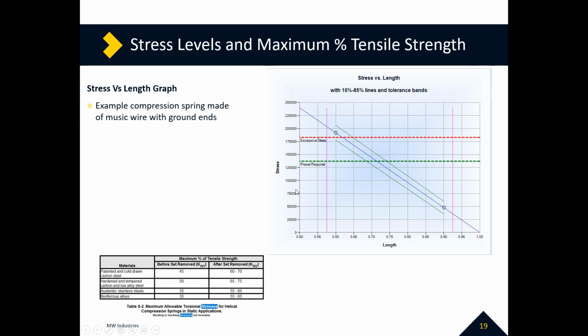This next slide we're going to talk about stress levels and maximum percent of tensile strength. So stresses are very key to a spring design. A spring manufacturer always wants to make sure we're designing to the lowest stress possible for the customer.